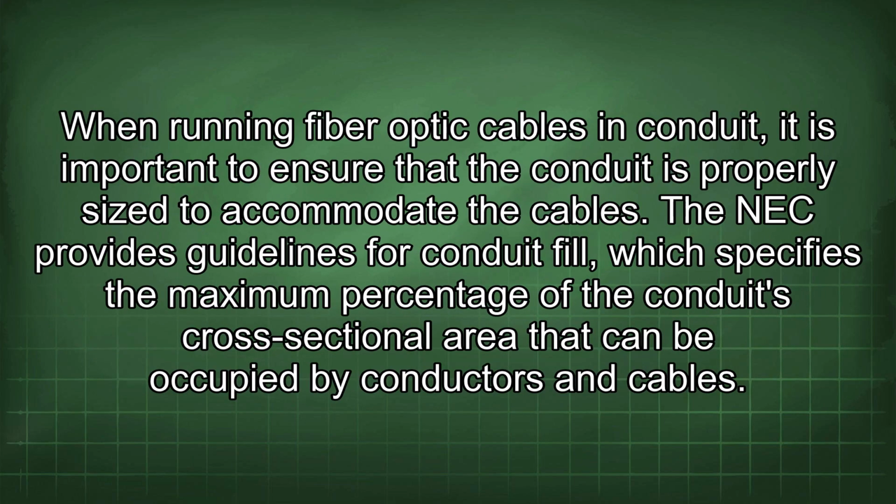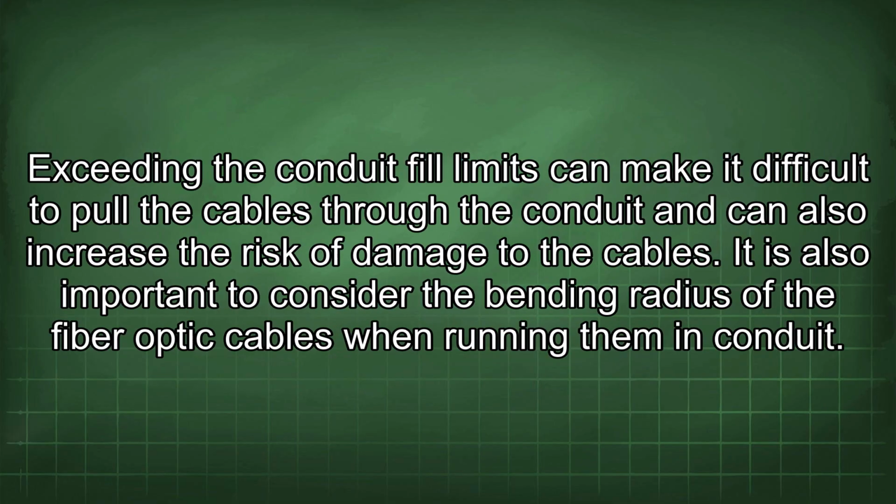When running fiber optic cables and conduit, it is important to ensure that the conduit is properly sized to accommodate the cables. The NEC provides guidelines for conduit fill, which specifies the maximum percentage of the conduit's cross-sectional area that can be occupied by conductors and cables. Exceeding the conduit fill limits can make it difficult to pull the cables through the conduit and can also increase the risk of damage to the cables.